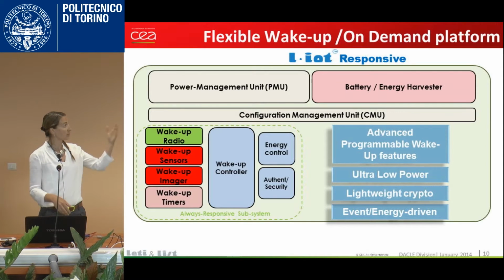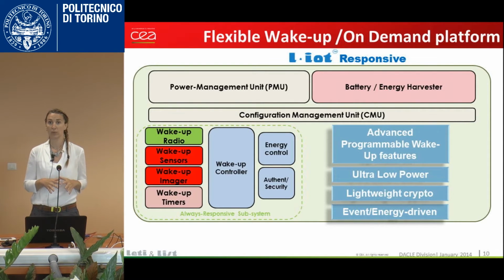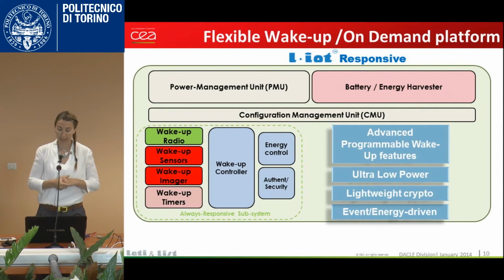So if we look at the responsive part, there are a lot of wake-up sources. Wake-up sources can come from sensors, but this is only wake-up. This is just maybe you cross the level of 100 Celsius for the temperature. We have wake-up radio. It means that we are just identifying something in the communication channel, but this is not a real communication. We have some wake-up on imagers. It means that we can maybe have a look on the picture and just see if the door is opening in a room. And we have some timers. This is the classical timer wake-up.